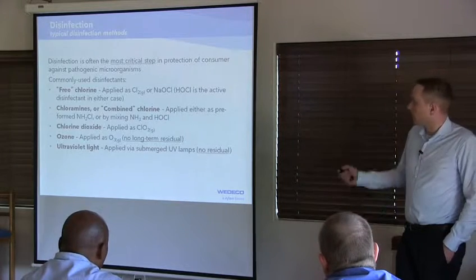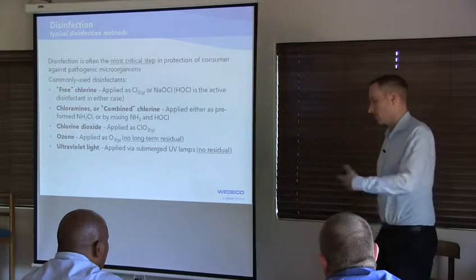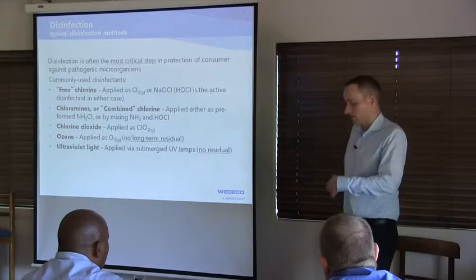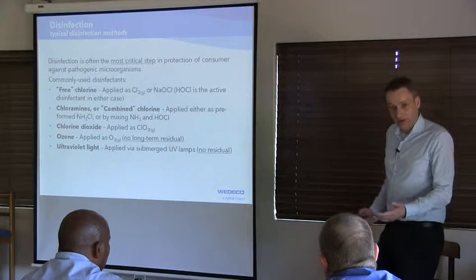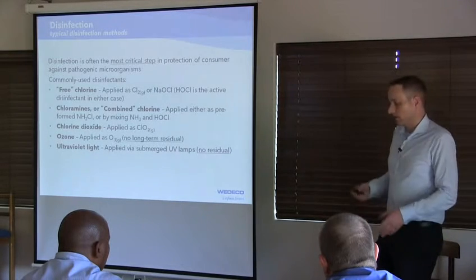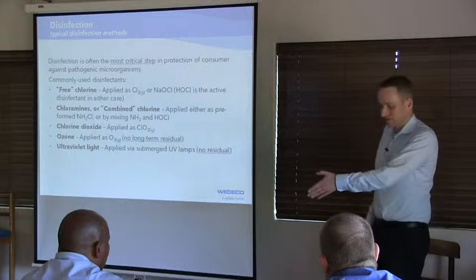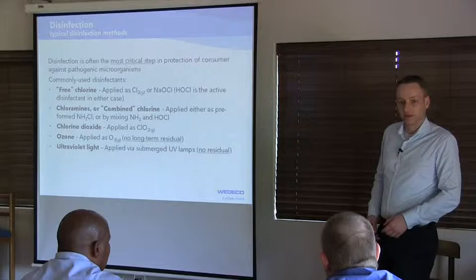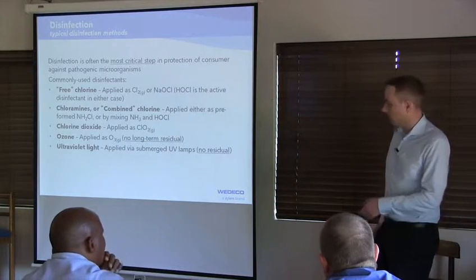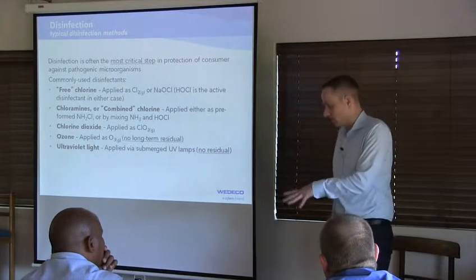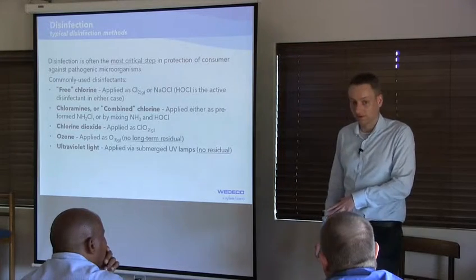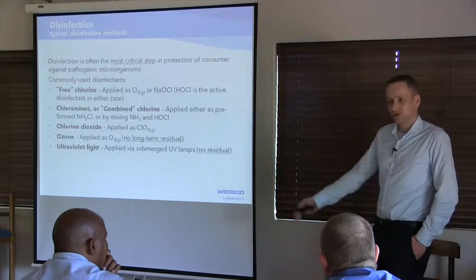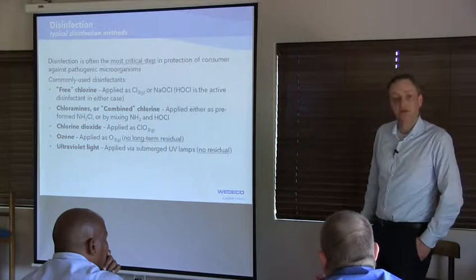Yeah. But they don't have the issue because the actual distribution net was built from when there was still big steel industry. So to prevent biofouling in any way, they drain the excess water back into the river at the end of the pipe, because the German population is not used to chlorine, they wouldn't accept that. So it is cheaper for them to just discharge the water back into the river. Yeah.